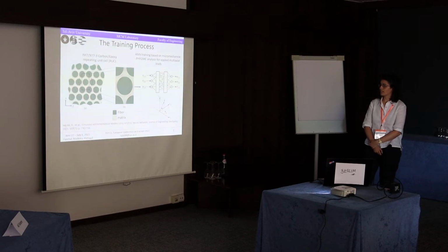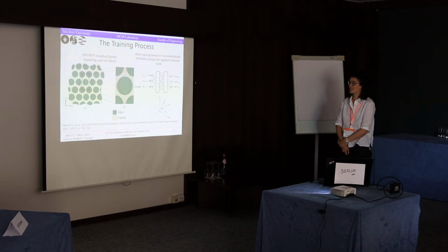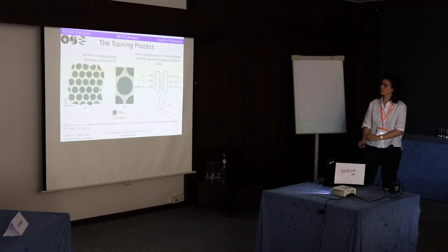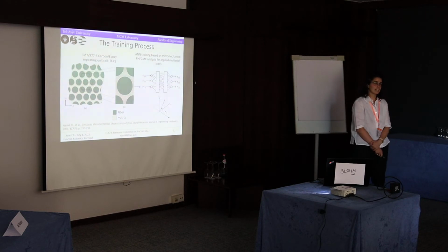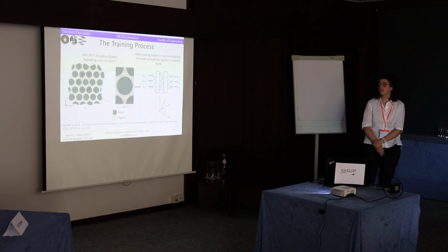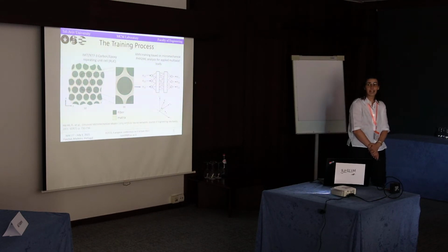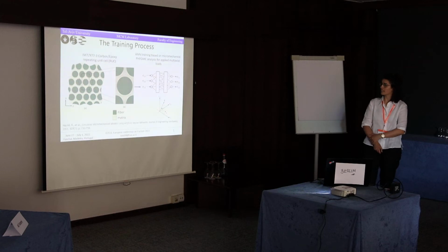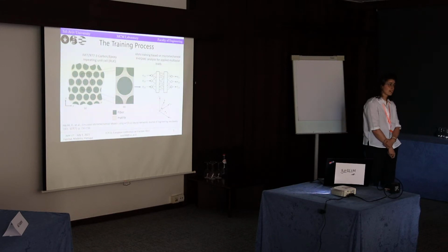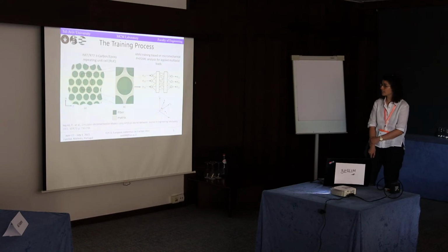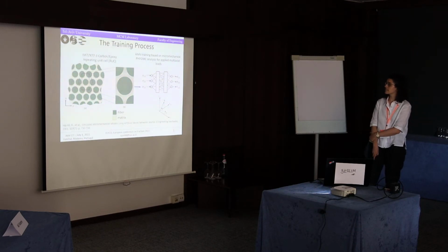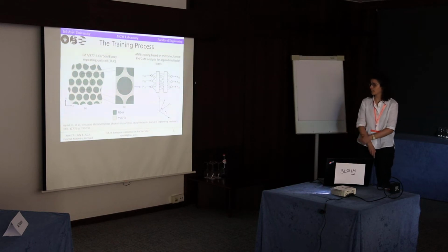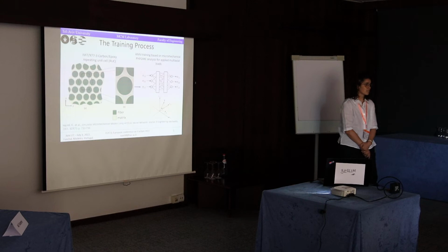And so here's the first artificial neural network. We took the RUC of IM7 977.3 carbon epoxy lamina, the ideal one, and we did a lot of PHF-GMC simulations on that for many multi-axial applied loads, and we insert into the ANN these strains as inputs and the stresses as the outputs, under the assumption of plane stress for unidirectional lamina. And in the training process, we insert the strain classes using the theta and alpha and the magnitude in order to allow systematic training and then prediction.